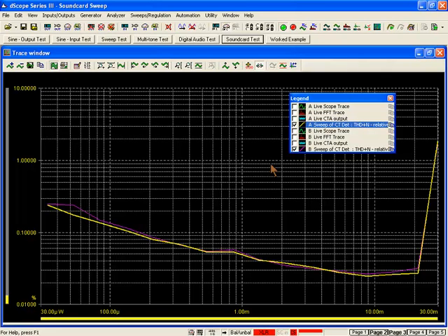So hopefully that now explains how certain types of playback devices, for example tablets and PCs, if they're running Windows as their operating system, we can greatly simplify the process of testing these types of device by using this closed loop measurement functionality in the Dscope 3 software, and preventing us from needing to encode and to play back wave files as we saw in the previous examples.